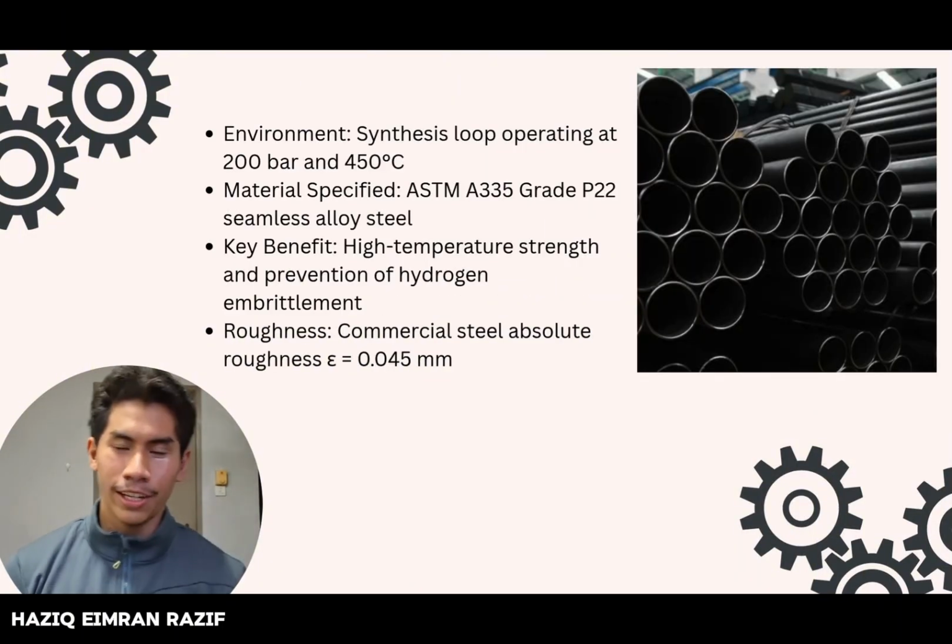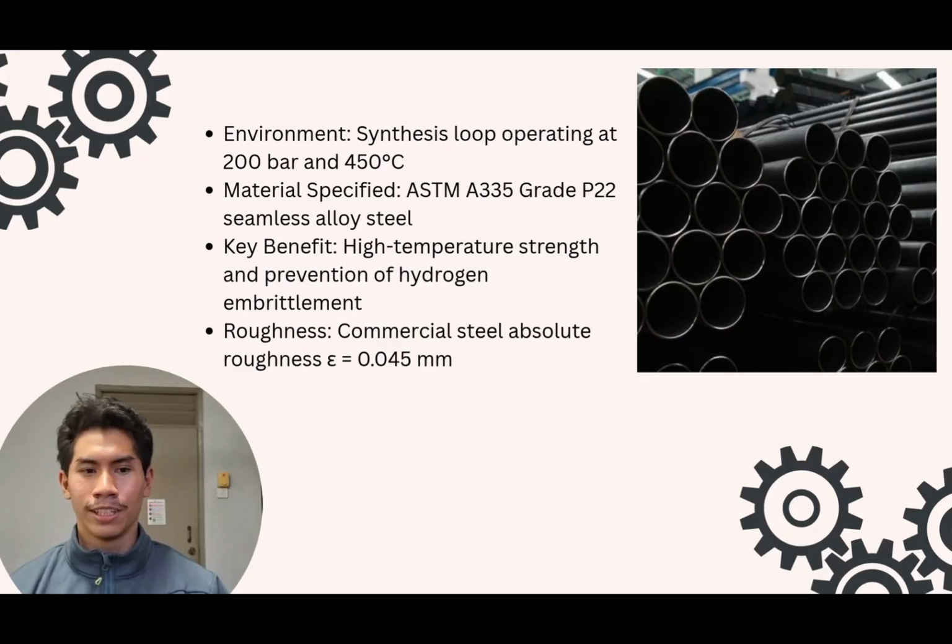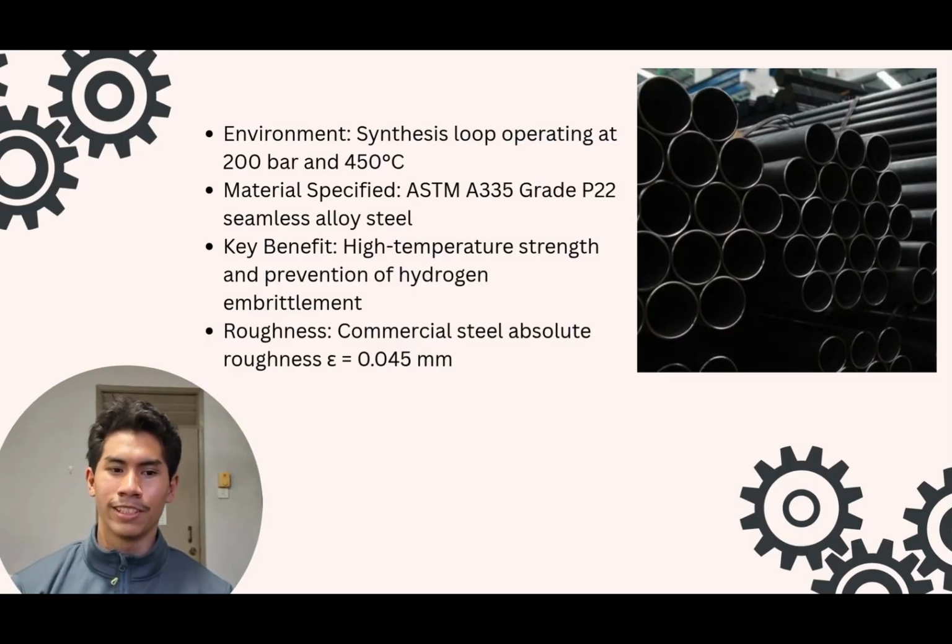Operating at 200 bar and 450 degrees Celsius, our synthesis loop requires rigorous material selection. We specified ASTM A335 grade P22 seamless alloy steel for its high temperature strength. Crucially, grade P22 prevents hydrogen embrittlement. We applied a standard commercial steel roughness, which is 0.045 millimeters.